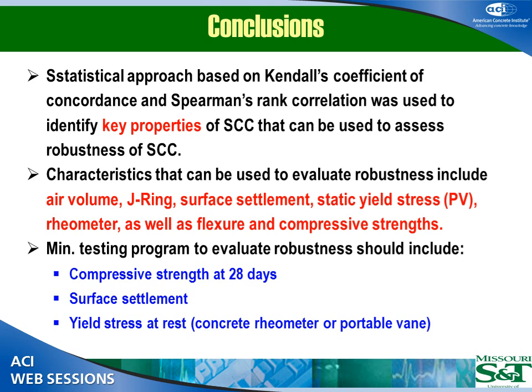Actually, the polycarboxylate we were using gives you inherent viscosity. And you know that. That's how you design it, right? So it takes care of the stability issues. But the variability, I mean, as you know, the response with PNS is pretty linear. So you add more, you have lower yield stress, higher slump flow, you add a little bit more, it's pretty linear. But with polycarboxylate, it's not linear. It's linear initially, but then it goes exponential, and then it goes back to linear. But that exponential is what throws us off.